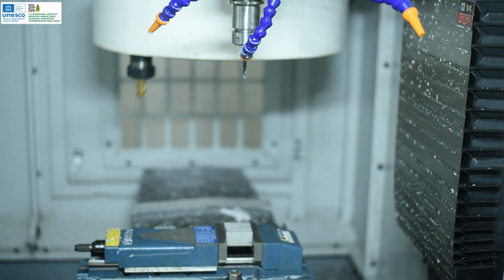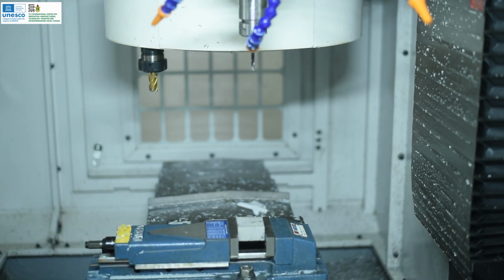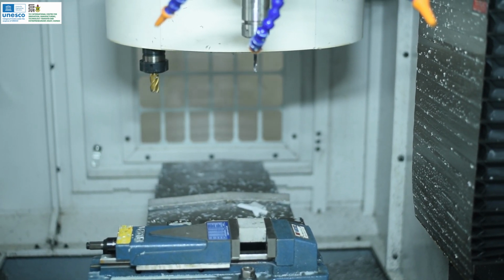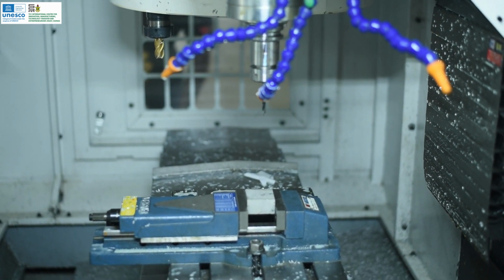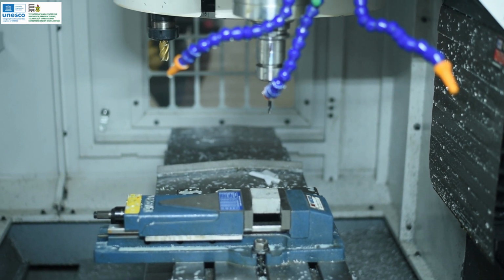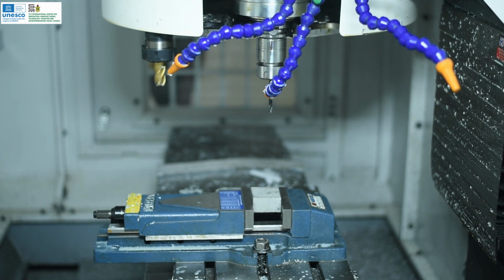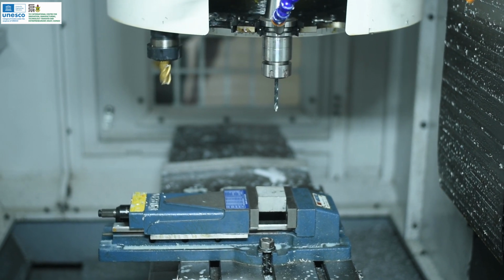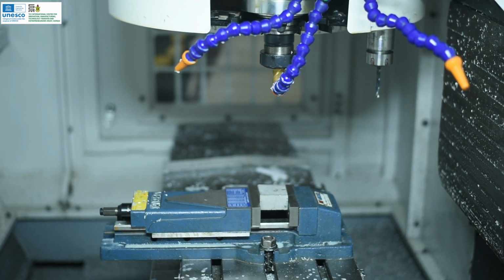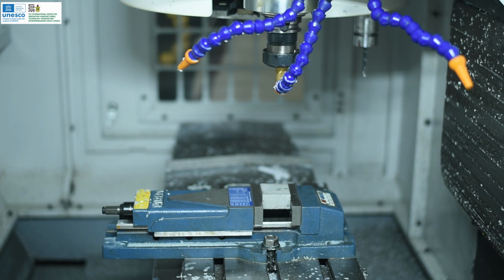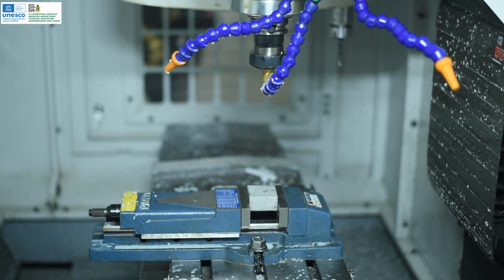The first thing, tool 2 is loaded, but it needs tool 4 first, so it's going to do a tool change. So we can watch it go down. It'll orient the spindle properly, bring in our umbrella tool changer, move up, change our tool. It's going to switch into the next tool, down, load that tool, and move our umbrella tool changer out. We can keep hitting cycle start.